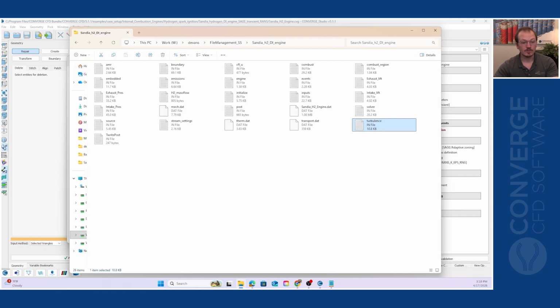The other type of file you have to deal with here are the data files, which are denoted by the .dat suffix. The data files used in CONVERGE can contain thermodynamic properties, chemical reaction data, and surface geometry information. For example, in the last stage of the CONVERGE workflow, you were introduced to the surface.dat file, which contains the triangulated surface geometry.